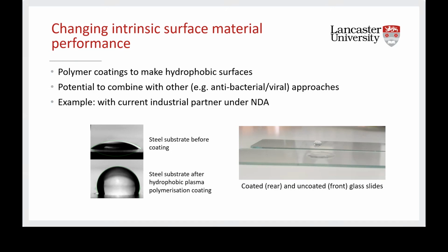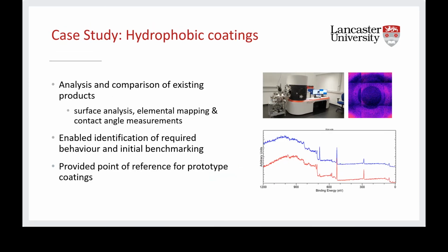I should say that the development of hydrophobics isn't something that's really new, but the specific applications may be, and we may be doing it in different ways to other people as well. So with this particular piece of work, we were given existing substrates, we were given alternate products. As before, our coatings development is optimized by surface analysis. This case is no different, so using XPS again, but also doing elemental mapping of coatings, taking contact angle measurements as it's supposed to be hydrophobic.